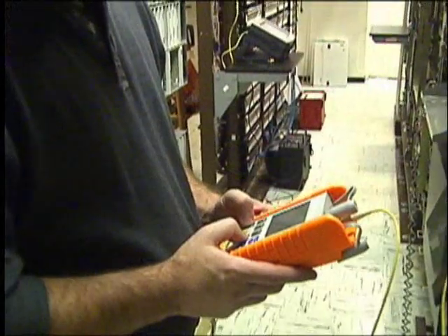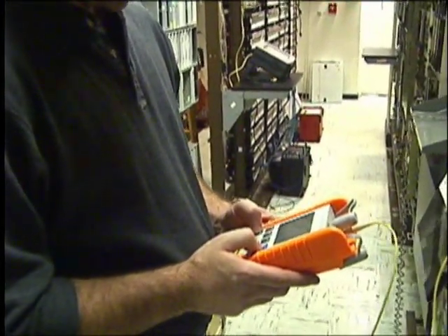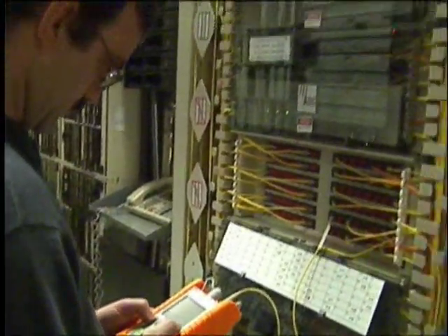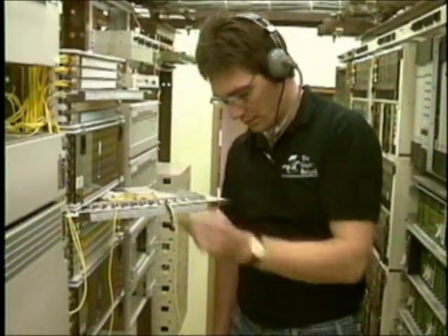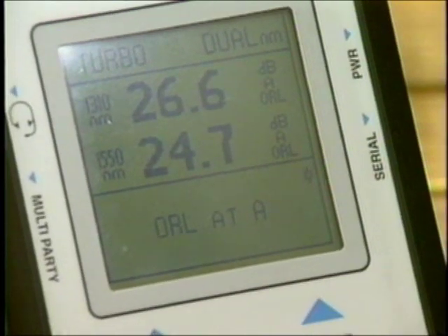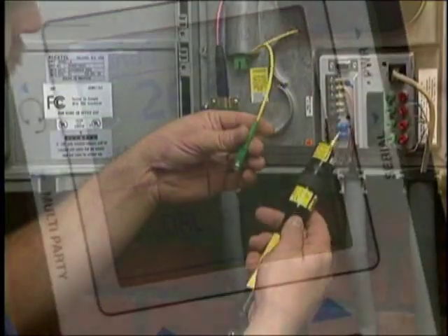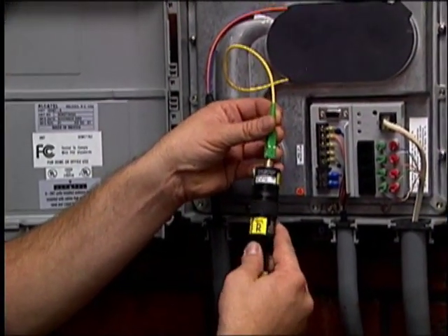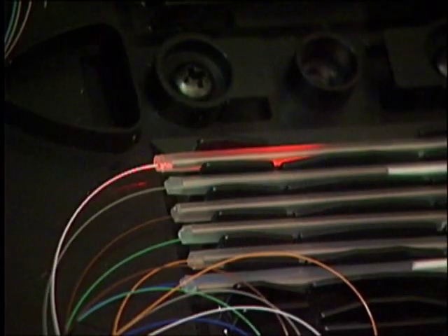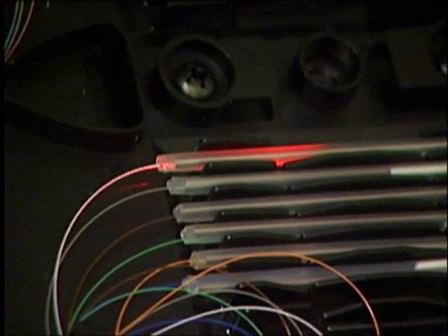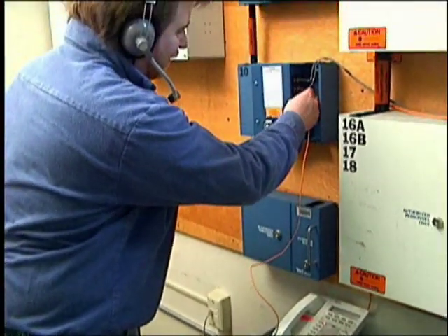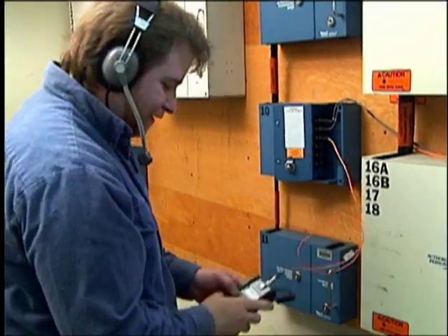For example, loss test sets, consisting of a stabilized light source and power meter combination, are used for testing the end-to-end loss of an optical span. Optical return loss test sets measure the total amount of light reflected back toward a transmitter. Visible fault locators inject light from a visible laser or red LED into a fiber, allowing the operator to see the location of severe bends or fiber breaks. Each of these instruments has its own benefits and attributes, and each can be used to test a limited subset of the complete fiber performance characteristics.